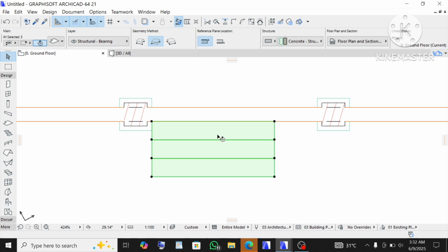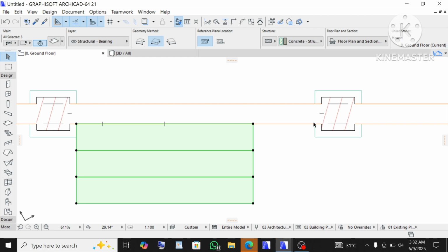So now we are going to position this at the center of here and here, but before that I want to measure this. I'll click measure, I will click from here and measure it to here, which is 700. That means I will drag this here by 350 mm.